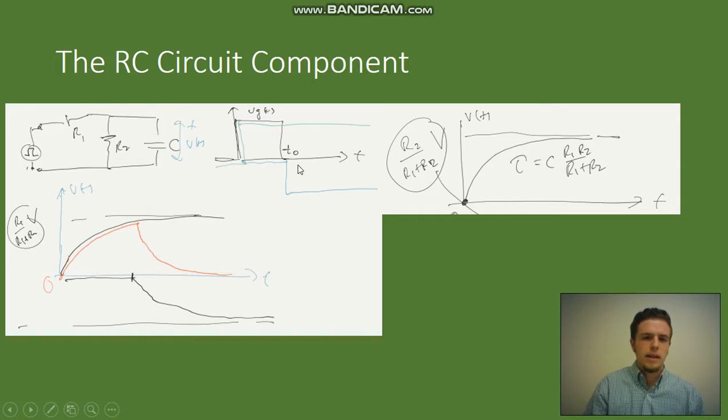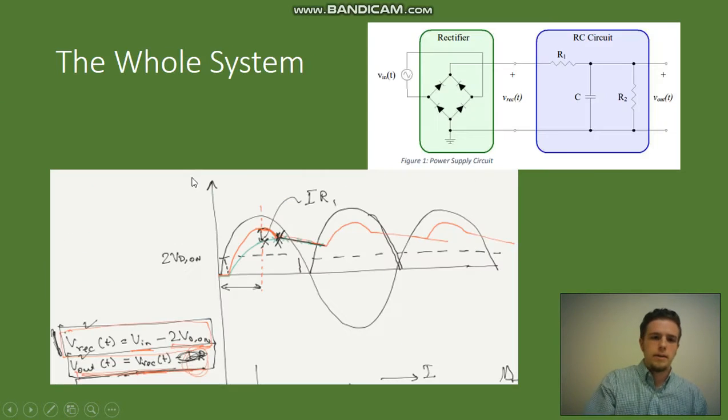And then you have the inverted and delayed step that when you add these both together, they give you the charge and the delayed discharge after that initial charge, giving you the shark fin sinusoid over the voltage over R1 and R2 in the voltage divider.